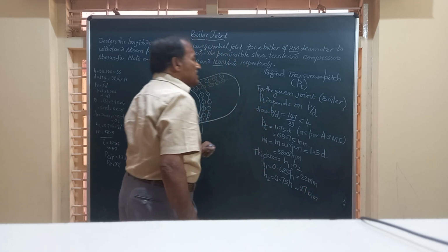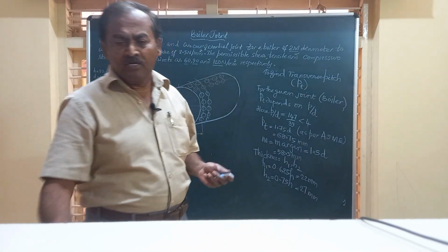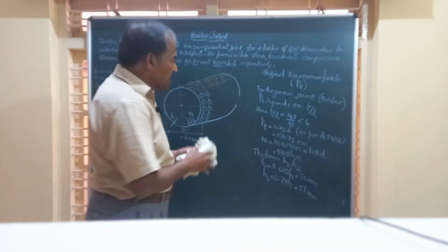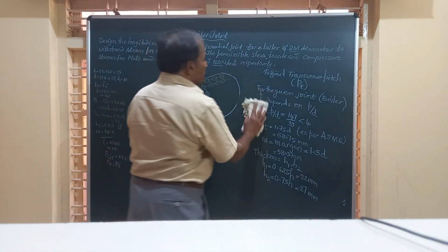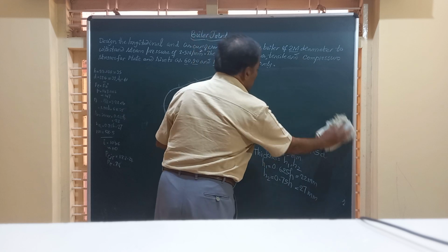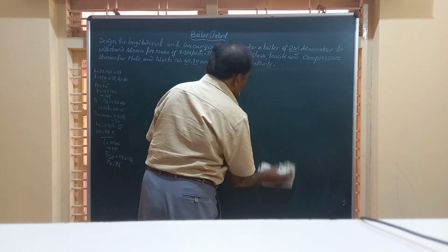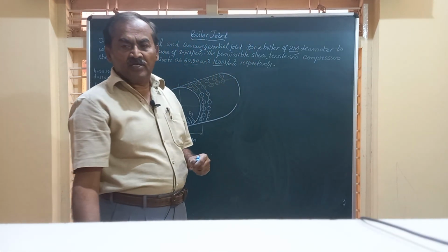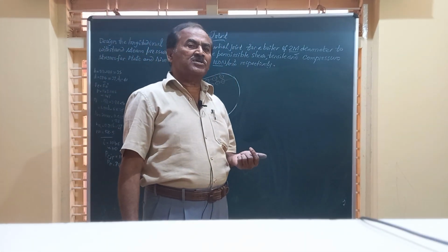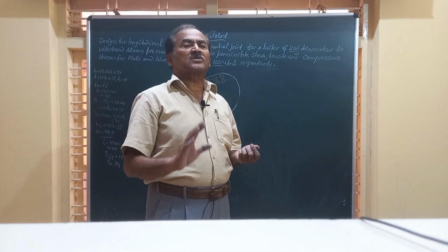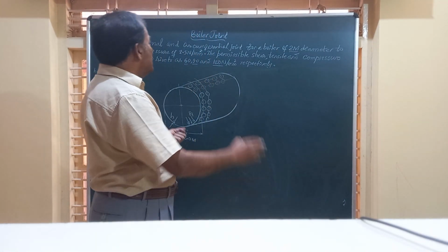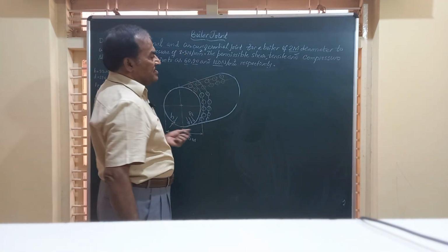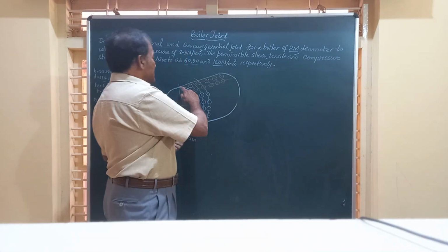So friends, with the given information, we are able to compute all the parameters required for this joint, namely the diameter of the rivet, the diameter of the hole to be drilled, the value of longitudinal pitch, the transverse pitch, margin, and thickness of the cover plates. So this is the design we have done for the longitudinal joint, that is along this length.